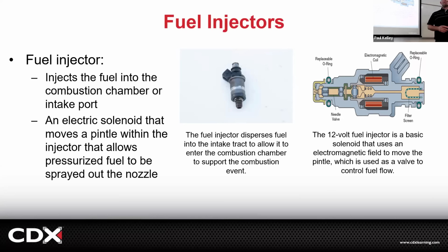All right, let's say you had a coil, this injector magnetic coil was open. Do you think you'd smell fuel? I don't think so. It just wouldn't open. So you'd have a cylinder that's misfiring, and you'd actually proceed with electrical diagnosis.